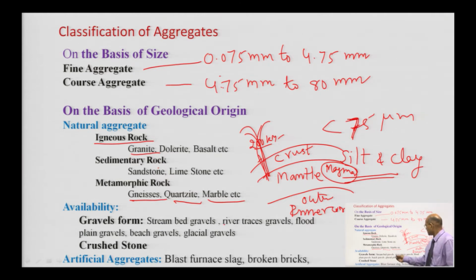Similarly, in rivers, there is a change of course of the river over geological time due to meandering and all that. So, there also you can find lots of gravel and sand particles that you can use, but they may be mixed with some silt or clay. If it is mixed with silt or clay, in that case you have to wash it.